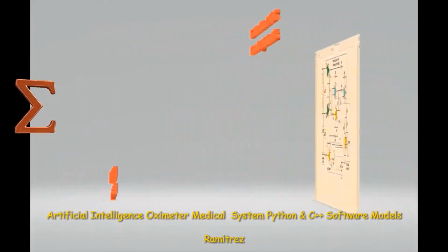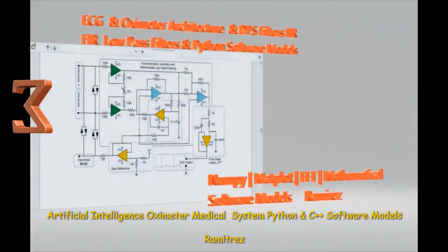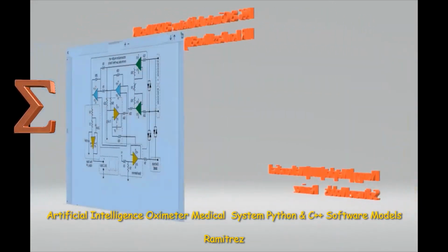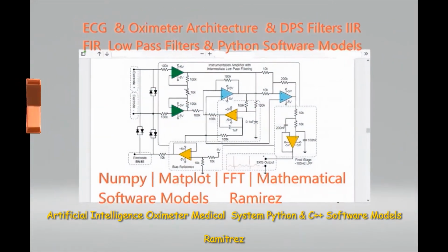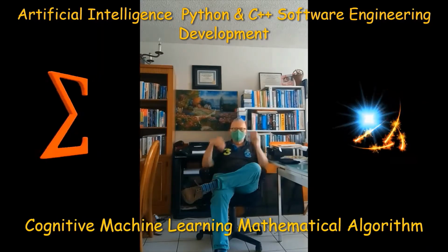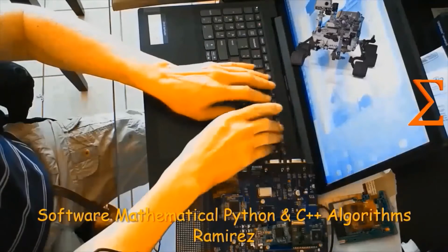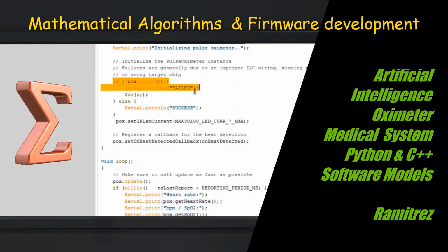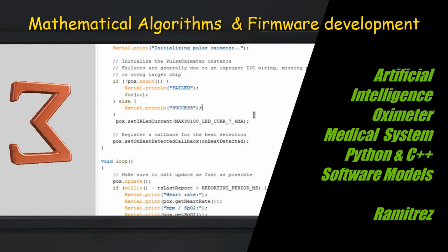This function configures the neuromorphic architecture to run in PLL mode, phase-lock loop mode, at approximately 96 megahertz of the core speed with a 50 megahertz clock to generate a system bus frequency.